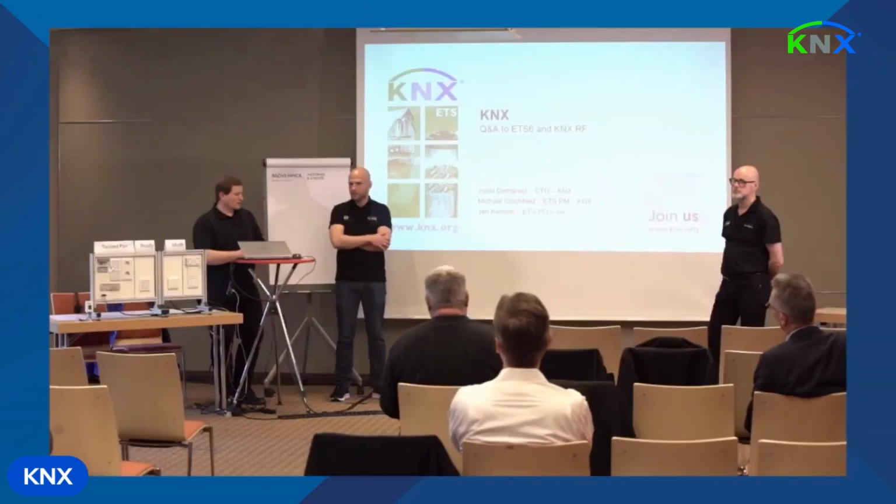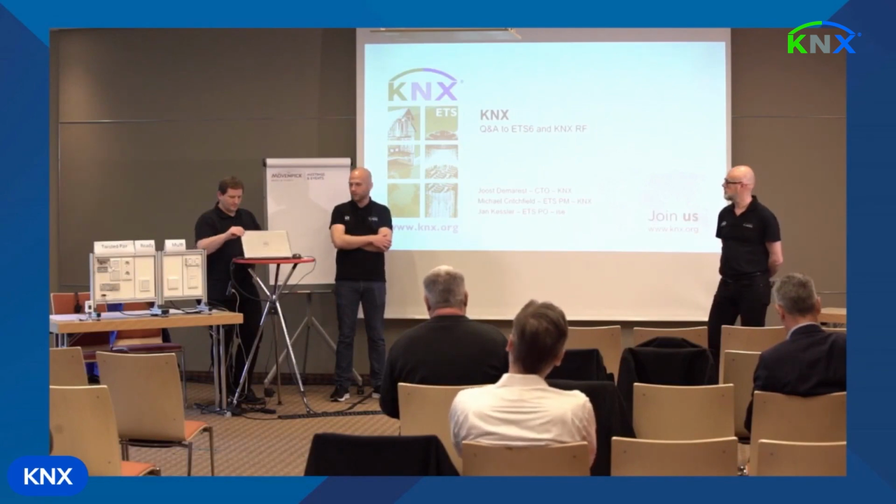In the background, a lot might have changed, and we have seen that in the background, suddenly telegrams are no longer ready, now they're multi. Previously, they have been unencrypted, suddenly they're encrypted, and all this happens in the background automatically configured by ETS. Yeah. But when you start, let's say, fresh in a new project, you would indeed be done much quicker. And you wouldn't have to deal with changing a line into a segment and making something secure back into unsecure and a multi-device acting as a ready device. This is not something you would do in a new setup.